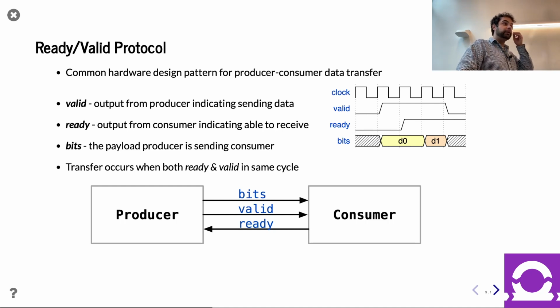So what was the iteration you wanted? Oh, okay, yeah, good question. So the question was, in reference to some of the alternatives to ready valid signaling, perhaps some that do the ready or valid a cycle beforehand. That is not baked into the standard library. The standard library is only this particular flavor. So yeah, that's right. Some people really stress out about whether ready valid is the same cycle or the cycle before, and that can sometimes get you some clock improvement for the critical path. You'd be surprised how careful design, even with this constraint of being the same cycle, you should get this right.